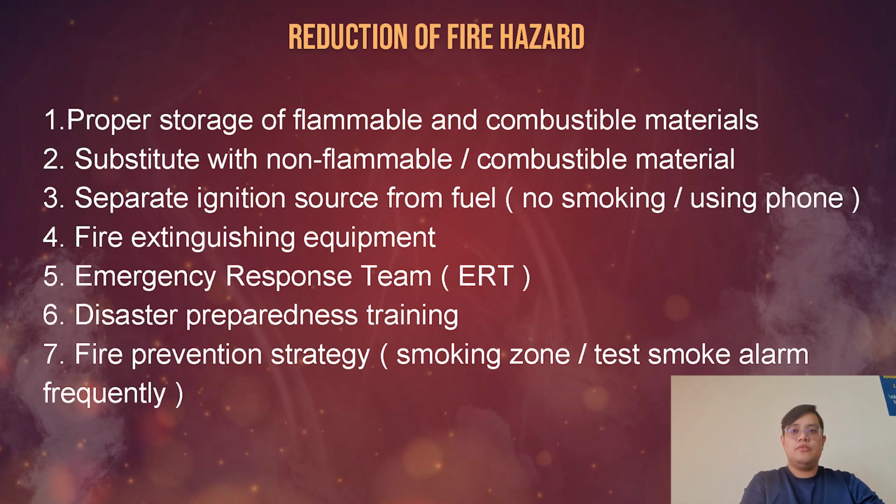Also, the company should provide a beam detector, which is a device that operates by detecting smoke using a projected light beam. The optical beam detector does not work until the smoke reaches the device mounted to the ceiling. The detector is attached to an alarm system. So when the beam detector detects the smoke, the alarm system will automatically send the warning to around the company.